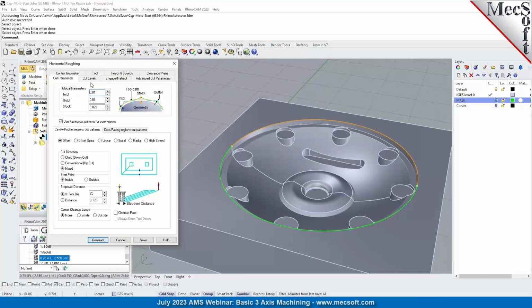anything. So the in tolerance and out tolerance: the way the tolerance is calculated in 3-axis is different than it is in 2-axis. In 2-axis, the tolerance only applies in the X and Y sidewalls, say a pocket, for example. In 3-axis, the tolerance is calculated across the surface contour of the surface. Which means you have the possibility of the tool being outside of the stock or inside of the stock or the part, and you can set the inside tolerance and the outside tolerance individually.